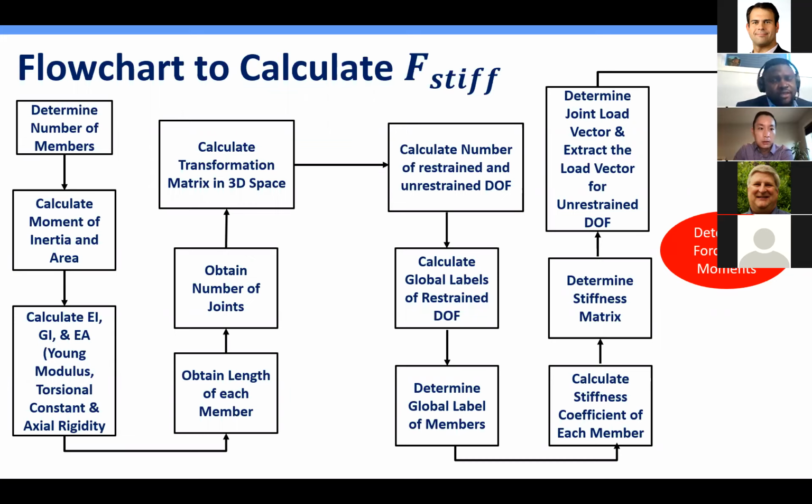Yes, so I think the one that would most likely underestimate will be the soft string model, right? Because you are assuming the whole drill string is in connection with the wellbore. So in both cases, depending on what method you are using, you have potential to overestimate or underestimate. So I think the easiest way to make sure you're doing it right is to compare your result with what you're getting in the softwares that are approved out there.